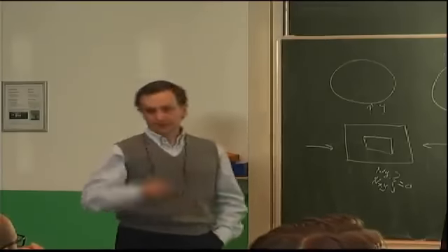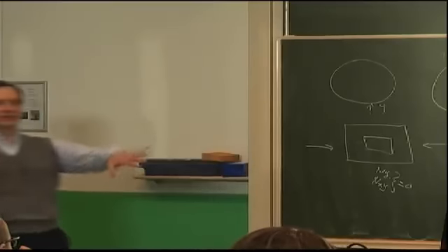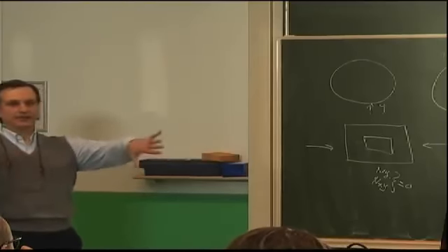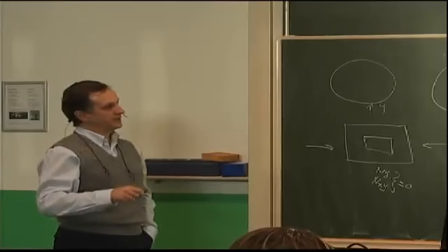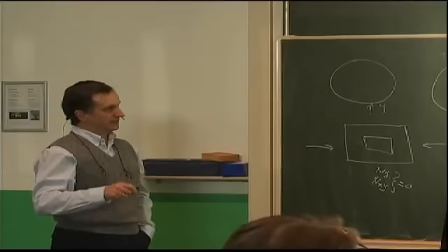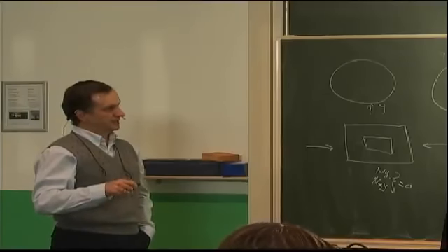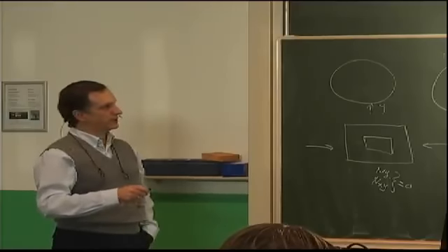But also, in the strict definition of simply supported design, where we allow the edges to rotate freely, there are no bending moments there. So the Mx is also 0 and the My is 0. So, in fact, these are the full set of boundary conditions. And why do I have 4 of them? Because it's a fourth order differential equation.